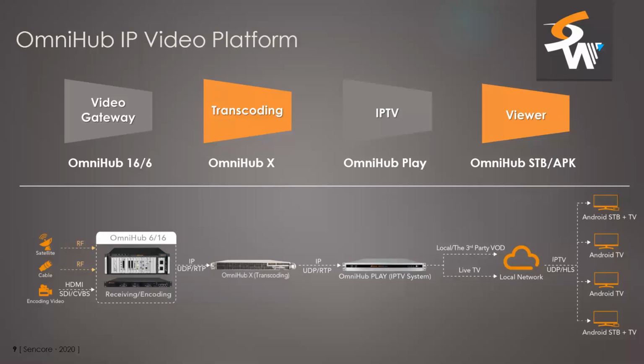I will talk about each product separately, but just to give a rough idea, starting from the left side, we have the OmniHub 16 and 6 chassis, which is a flexible head-end in a box type of platform with multiple inputs and outputs, providing signal sources for the system. OmniHub X is a software-based transcoding platform supporting both linear and OTT transcoding. So whenever you need to change the video codec, bitrate, resolution, or transport stream wrapper, OmniHub X can do the job.